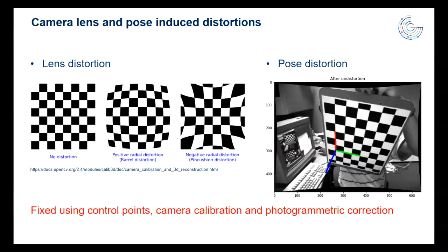Now, in truth, this doesn't have a huge impact on your PIV measurements, as long as one thing is true, and that is that your displacements are small. Right? If your measurements are staying in the same location in the image, this distortion doesn't matter, because you're going to have the same distortion in both your reference image and your target image. Okay? But the minute you have soil moving from one side of a model to the other, the distortion is going to change between the images in the sequence, and all of a sudden you're going to entrain errors in your measurements. So in principle, what I say is photogrammetric corrections are a nice thing to have. If you have sufficient information to reliably account for these distortions, you should correct for them.